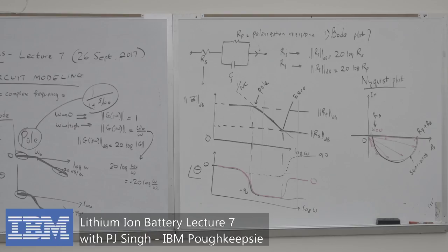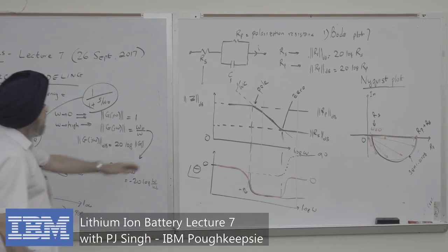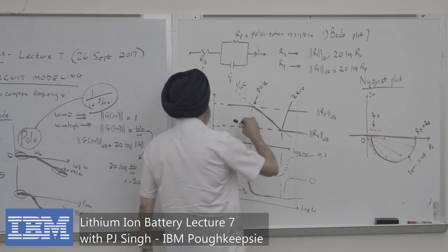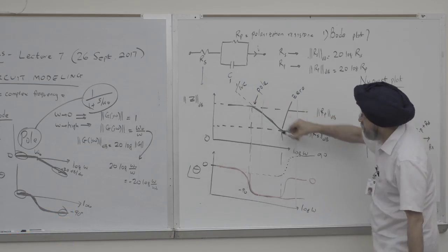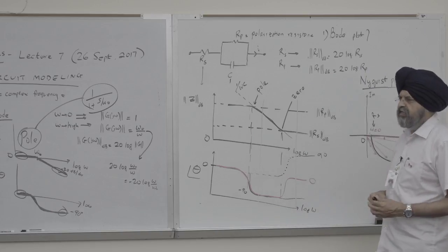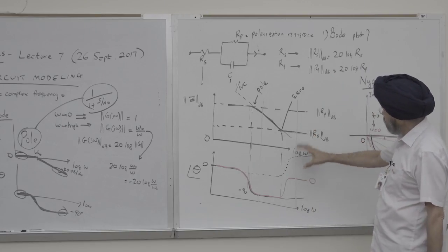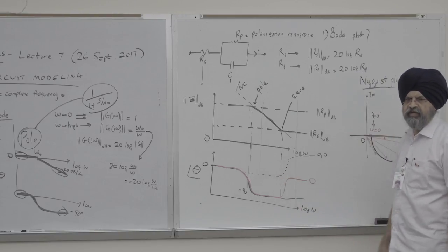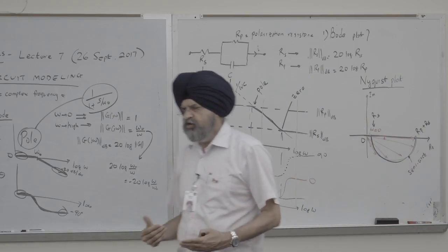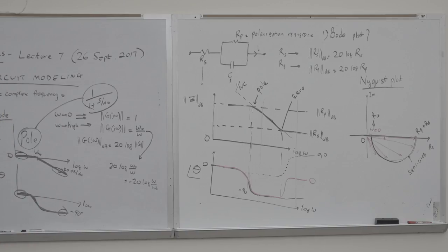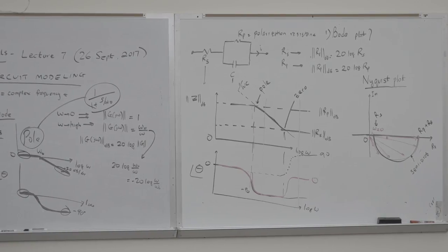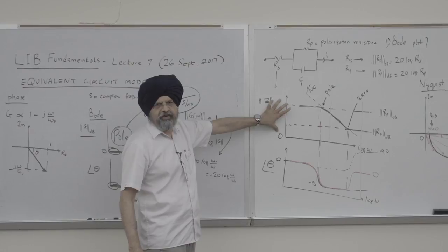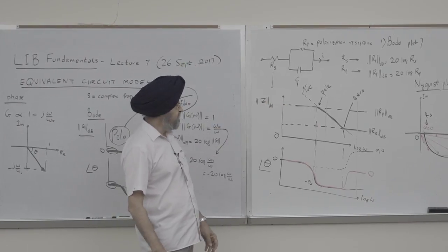So for example, I missed the step: why do we add the Bode plots? In other words, we had 2 Bode plots. Well, actually we had 3. We had Bode plot for 2 resistors and a capacitor. Why do we add them up? I ignored that step. And then I also said the phase plots also we can just do a simple arithmetic addition. The reason we can add them up is because when you take a log of multiplication, you're actually adding. Because we are on a log scale, when we multiply terms, the log terms are added. That's the reason why.